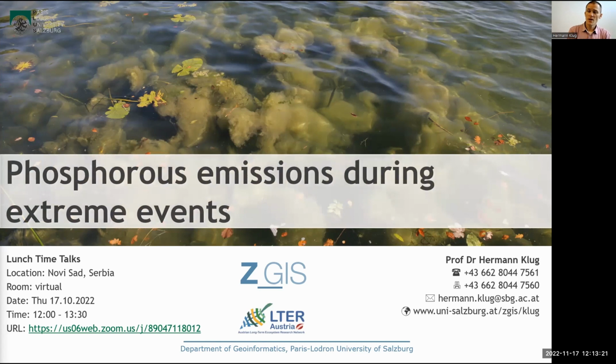So what we are looking at here is the limiting agent in this aquifer system, and this is phosphorus. So there's a lot of nitrogen available, but if you put 1 drop of phosphorus to it, then these algae blooms start. So we had to look at phosphorus emissions, and we had to ask ourselves, okay, when are these emissions taking place? Of course, during the fertilization processes, but are these the ones most important? You can infer from this title, which I put here, that phosphorus emissions mainly result from extreme precipitation events.